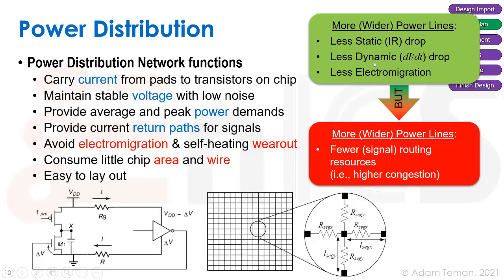But also we have this thing that is dynamic IR drop, a dynamic voltage drop. So we have V equals L di/dt, and the thing is that these are rather constant, you would say. You have some sort of average current, and that's fine. The inductance over our whole chip that's caused by these loops knows how to hold this constant current.